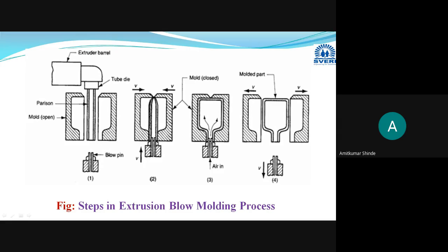Placing and closing of this mold cavity, this will be the second stage. Then with the help of the one pin that will be termed as the air pin, we are going to pass compressed air, and that compressed air will perform the inflating of the tube. Inflating of the tube, or blowing operation, will be performed here with the help of this